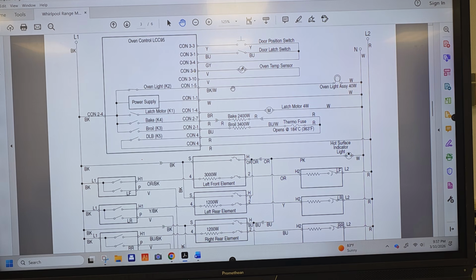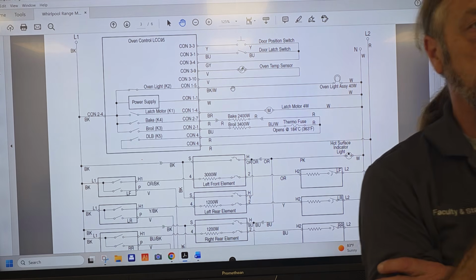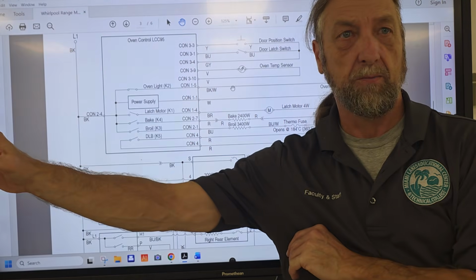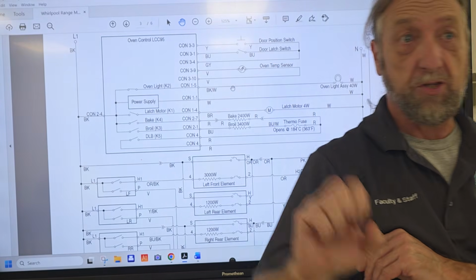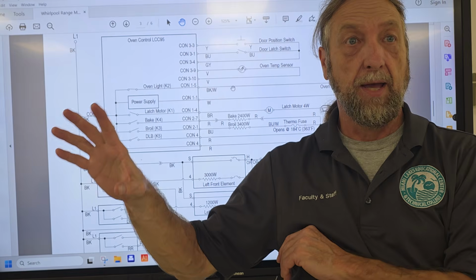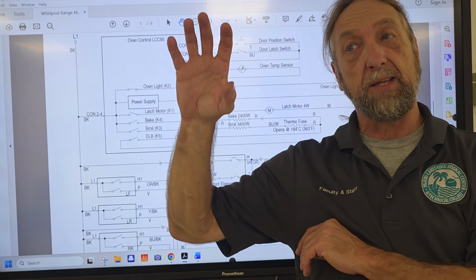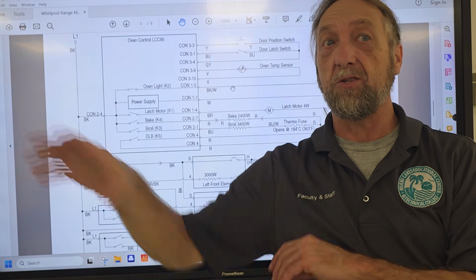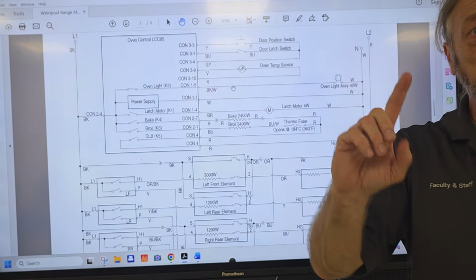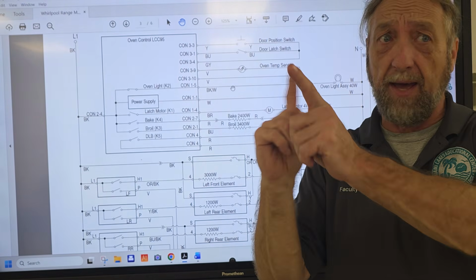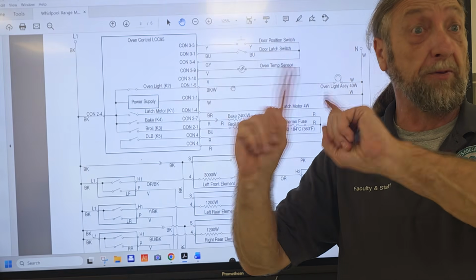With an oven temperature sensor error code, the board is always checking the sensor. It's always sending a little voltage. When you first turn it on, the oven's cycling, and you turn it off. The board is not checking whether or not the elements work. The first thing it does when you turn it on is look for that 1,000 ohm range, roughly.